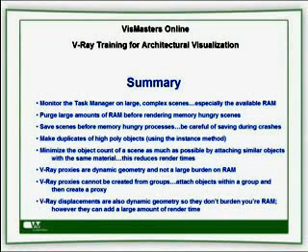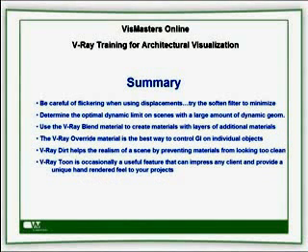The VRay displacement modifier is a great feature that can do for the realism in your scene as much as any other feature. It's dynamic geometry, so even though it can add some render time to your scene, it at least isn't as much of a burden to your RAM. It's difficult to create animations with this modifier without the effect of flickering, so always test a small portion of your screen prior to rendering a long animation. And speaking of dynamic geometry, figure out what the optimal dynamic memory limit value is and use that value. Too high or too low of a value can drastically increase your render times.